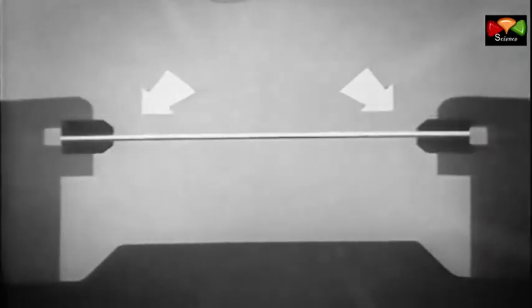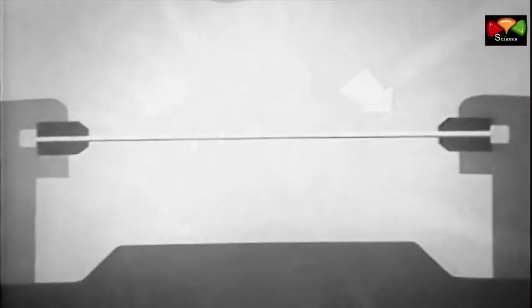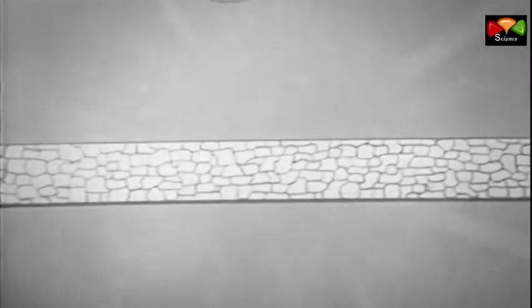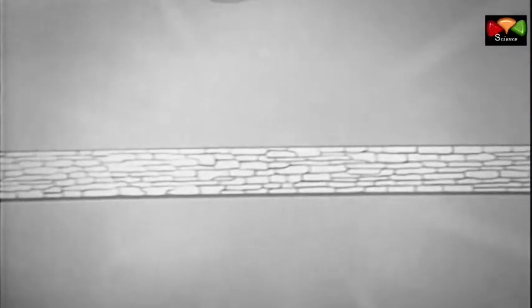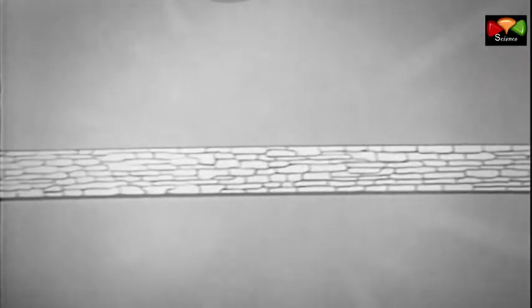The stretching process is based on the action of vice-like grips, in which the edges of the aluminum alloy section are inserted. As the tensile load is applied through the grips, the metal is stretched, the equiaxed grains becoming elongated and oriented in the direction of the applied load. These grain changes increase the strength and hardness of the metal.